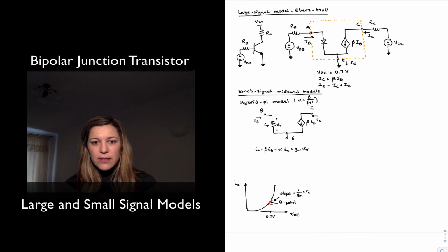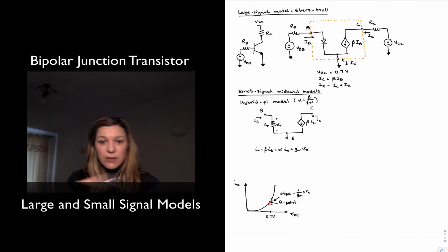The reason is the resistance that we are seeing here is actually the diode resistance, if you will, from base to emitter, but we're looking from the base terminal. And if you remember, when we look from the base terminal through the transistor, what we're going to see as the resistance connected to the emitter is whatever resistance is there multiplied by a factor of beta. And so that's actually the relationship between r pi and little r.